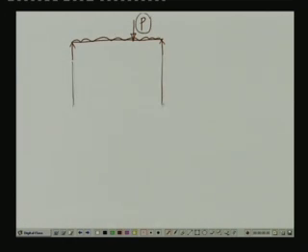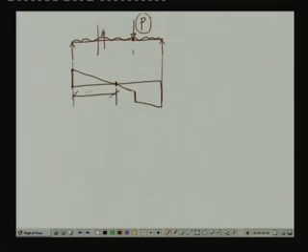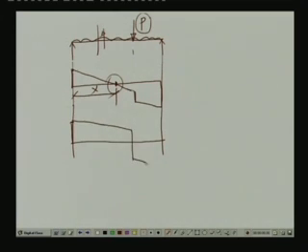Now, the shear force diagram can be like this: at this point it goes over here. If you take a section, you can place the shear force V equal to the load W times X minus this reactive force. Since you have a uniformly distributed load, it comes down, then at the load point it comes down, then further it goes down and comes over here. There could be a diagram like this wherein we get a 0 shear force here at some distance, let us call this X. Or we can have a situation where the shear force may not be 0 at this particular place; it will go here, then it comes down, at the load point it crosses, it comes over here and then comes like this. So, the shear force diagram could be like this as well.